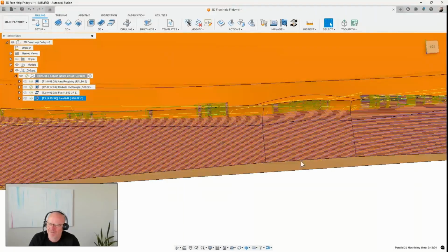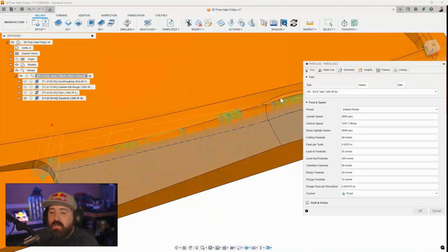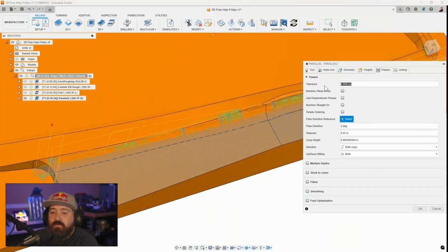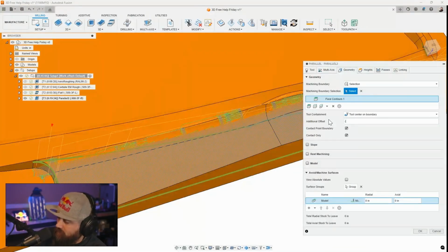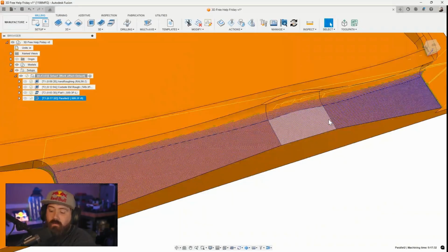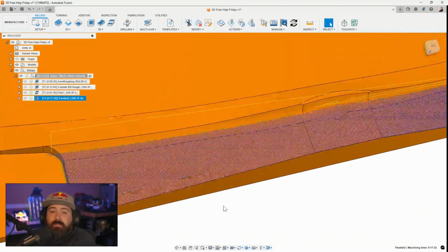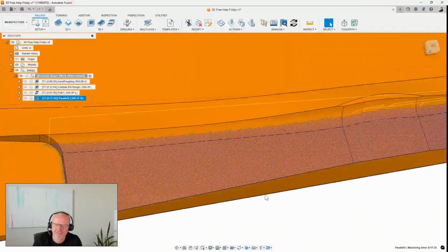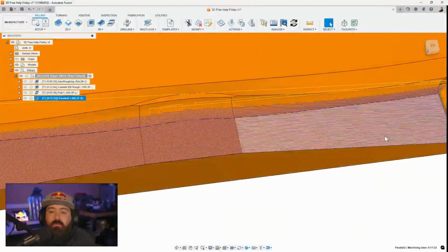We get a little bit of noise here, right? I taught you guys a couple weeks ago how to finish this noise. Get this tolerance right here. We can say negative tol, or if you're an ape like me, I'm just going to type in -4 tenths. And there we go. Thoughts on this, boys? Yeah, not ideal on the fillet side. On the flats, it's good on the flats. Flat side is good because it matches up here.